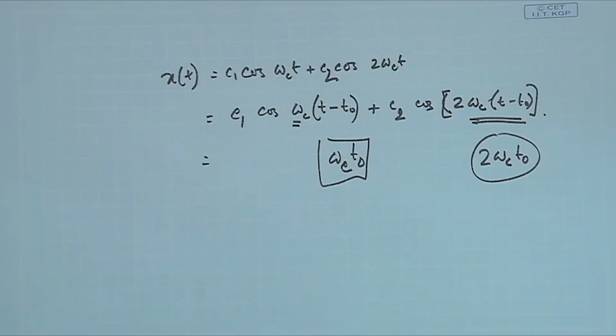That means if a constituent signal is composed of multiple frequency elements, they will be separately delayed. So after the Hilbert transform you will not get back a similar signal, whereas with a pure delay the composition of the signal remains the same. So there is a difference between delay and this one.